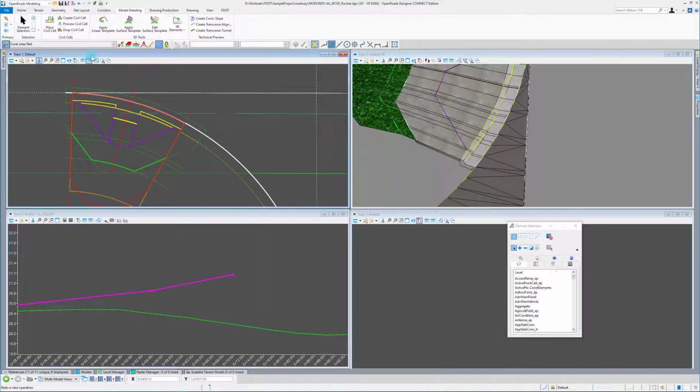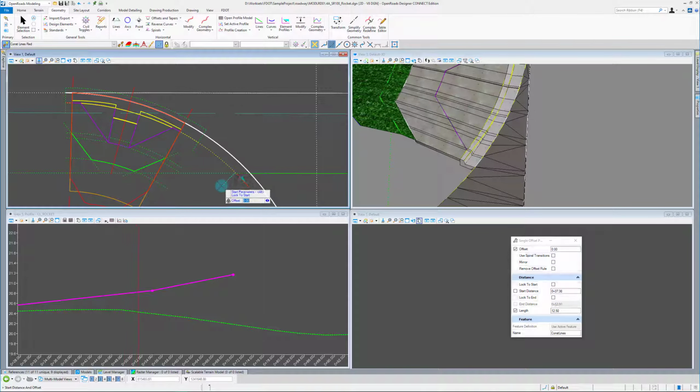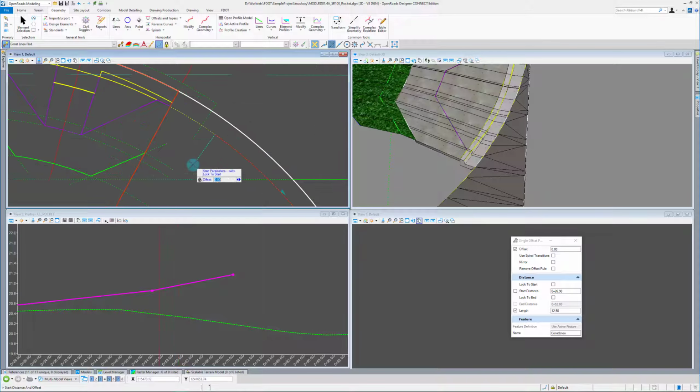And I know my CRD, so we're going to do a single offset partial. Between adjacent curb ramps, you need to make sure that you have 4 feet of full height curb. So I could go from here, but for this instance, we're just going to go from right here. This is where the sidewalk comes in. Then we'll make sure we have a nice 4-foot full curb, sidewalk, everything.